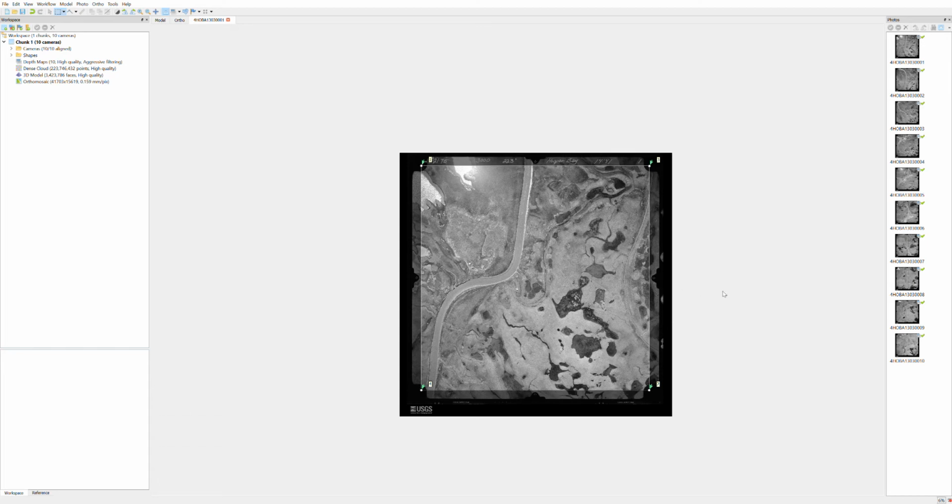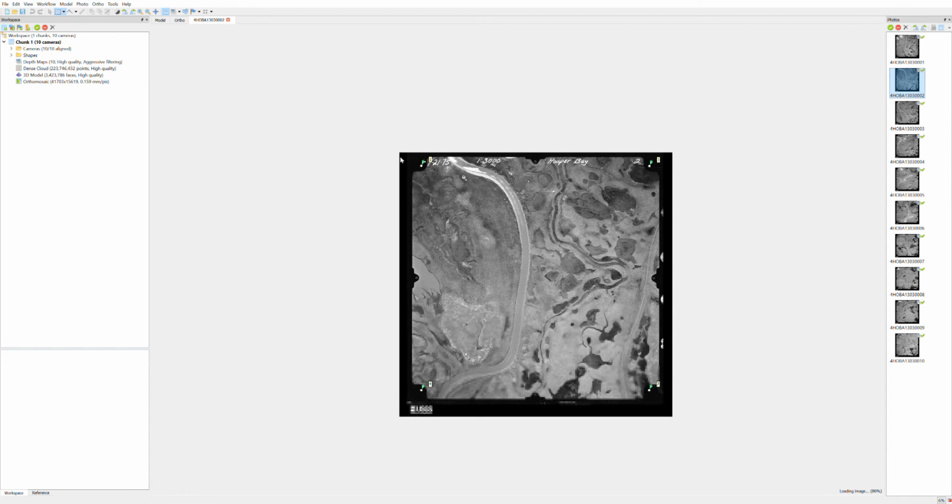So one thing you could do is just use the steps to save your mask and then import to all images, but I only had 10, so I just do this for every one. So again, we'll do this here, drag down, Control-Shift-I, Control-Shift-A. So once you have a mask for every image, we can move on to our alignment.